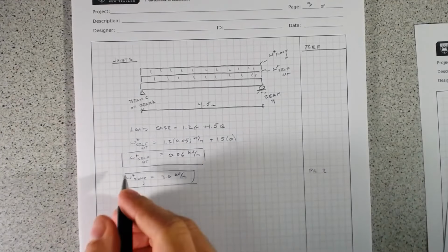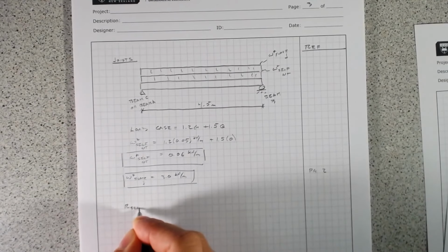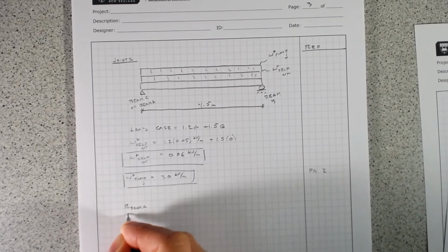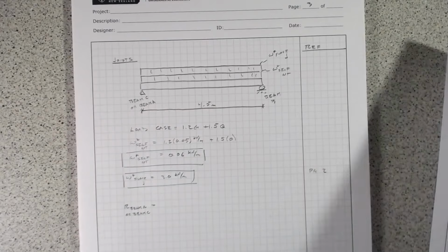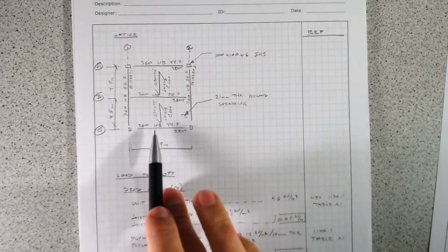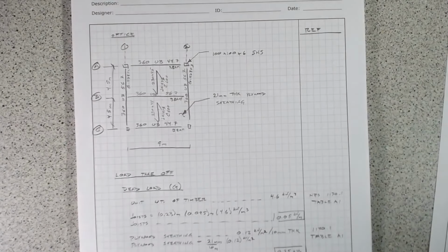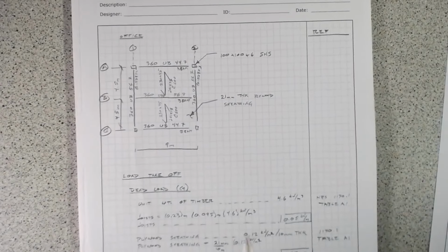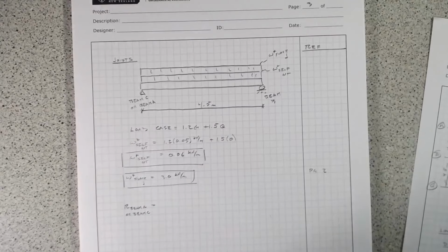So if we work out the reaction of beam A or beam C, so that's this side, that'll be the reaction that the joist is putting in, for these joists over here, putting into beam C. For these joists here, the reaction putting on to beam A. And always keep in mind that the reason we're doing this is we're trying to trace loads down and see how they collect through the structure.